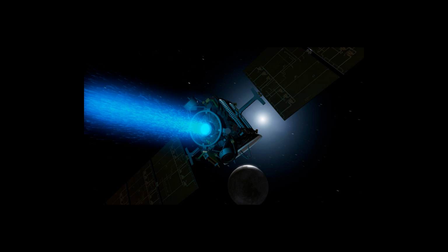So as soon as you want to go into the outer planets or towards Pluto, for example, with a space probe, and you want it to be able to fly several high delta V maneuvers and thus want to use an electric space propulsion system, this is probably the propulsion to go to. Also, you'll probably need an RTG for onboard computer power if you go far away from the sun, so solar panels don't really work anymore.